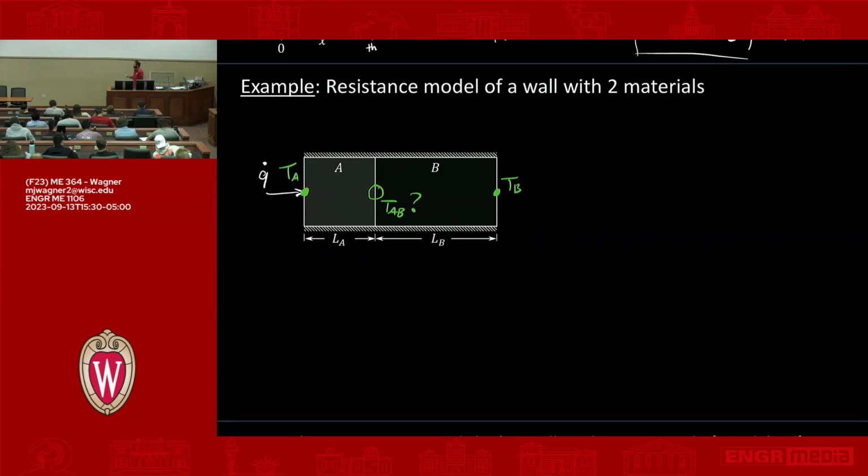So we can take this idea of thermal resistance and start applying it. We start stacking it up in this sequence, and we get back useful information. So how do we do that? Let's remember, if we have just one material, it's a temperature boundary condition. We can write it in terms of thermal resistance. So the first thing we're going to do is draw this resistance network. In this case, we're going to start on this side with our node TA.